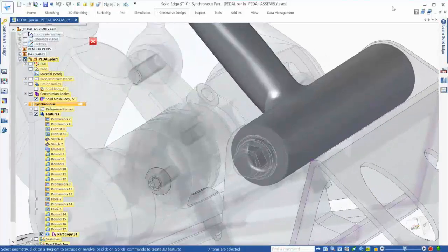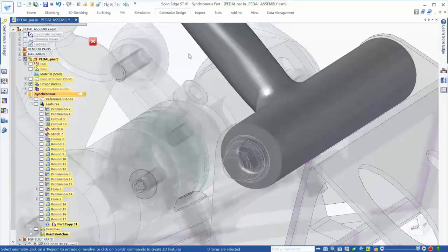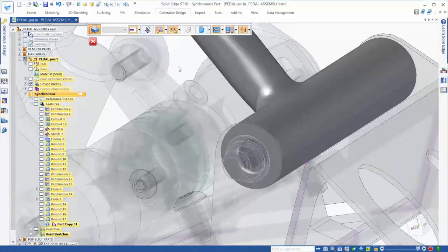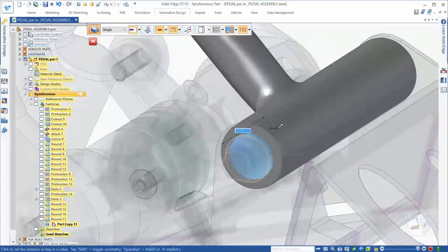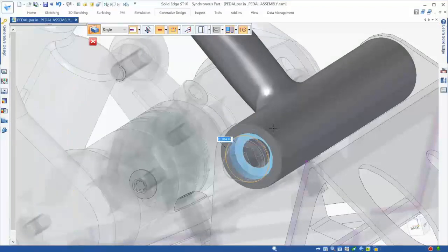The huge advantage in using Solid Edge to create and work with these generative designs, which are essentially mesh models, is when it comes to the creation of additional features that the design may need. With Solid Edge, adding and removing material is simple and fast. For example, a cutout can be added to the lower boss for the purpose of placing a bushing.